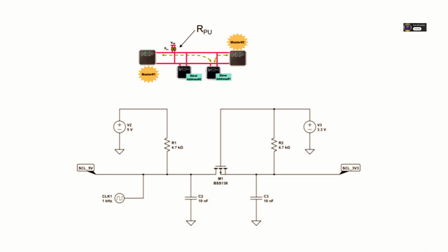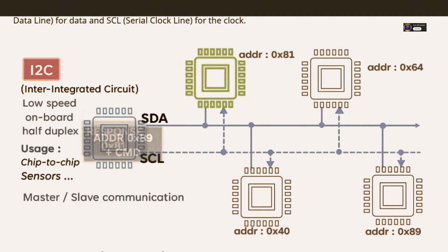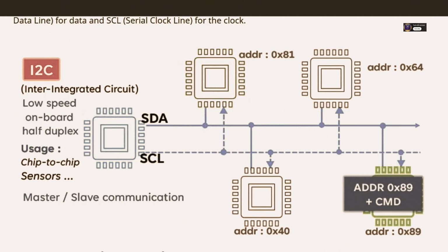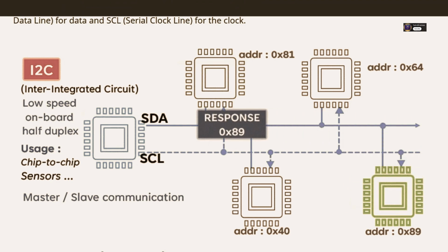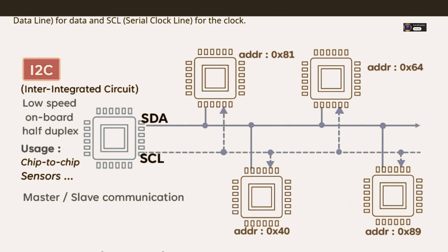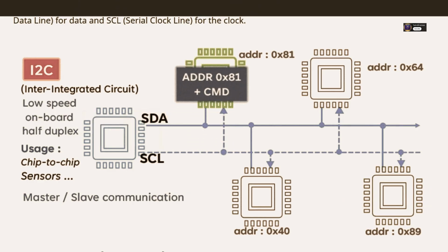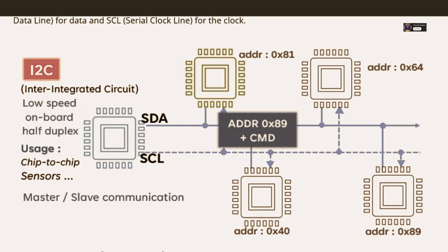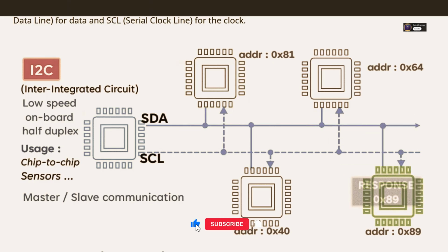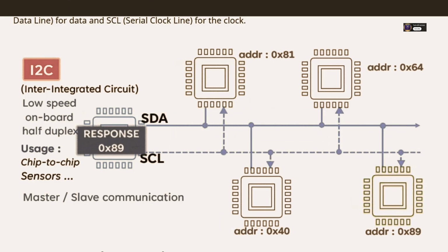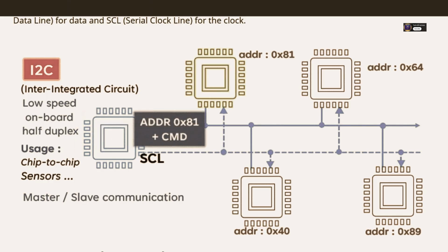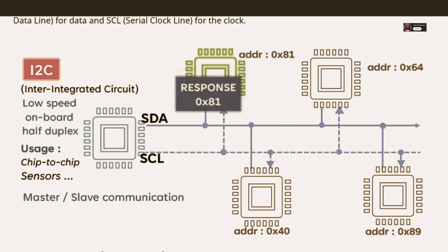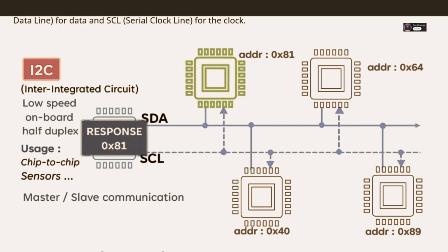Good to know. Are there any sort of variations or related technologies or ways to make I²C even more efficient? Definitely. One you might hear about is SMBus, the System Management Bus. It's basically a derivative of I²C, built on the same foundation, but with stricter electrical specs, tighter timing, and crucially defined command protocols. You see SMBus used a lot in PCs and servers for system monitoring, reading temperatures, fan speeds, battery status in laptops. It's designed for that kind of critical system management role. Very similar, but with more rules than basic I²C.